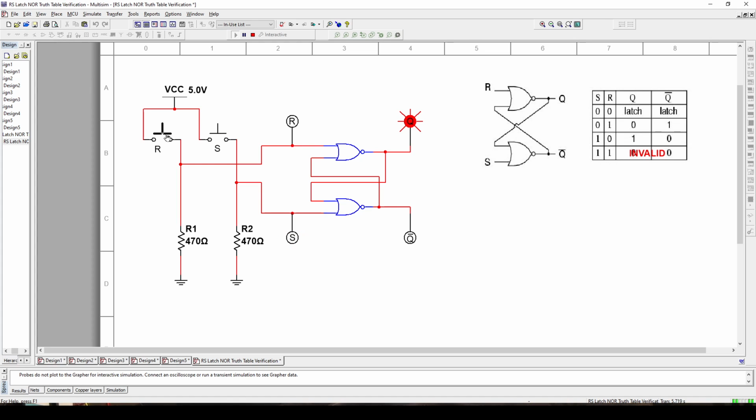All right, then if I press the other one momentarily, things are going to change in the reverse order. So here's the thing: if we can just press it for a very short time, why would we supply a clock that is longer? So if we're going to supply a clock, we're going to try to make it pulses instead of the whole square wave. Okay, we're going to talk about clock in the next coming videos. All right, so let's press that momentarily, so the Q bar should light up instead of that.